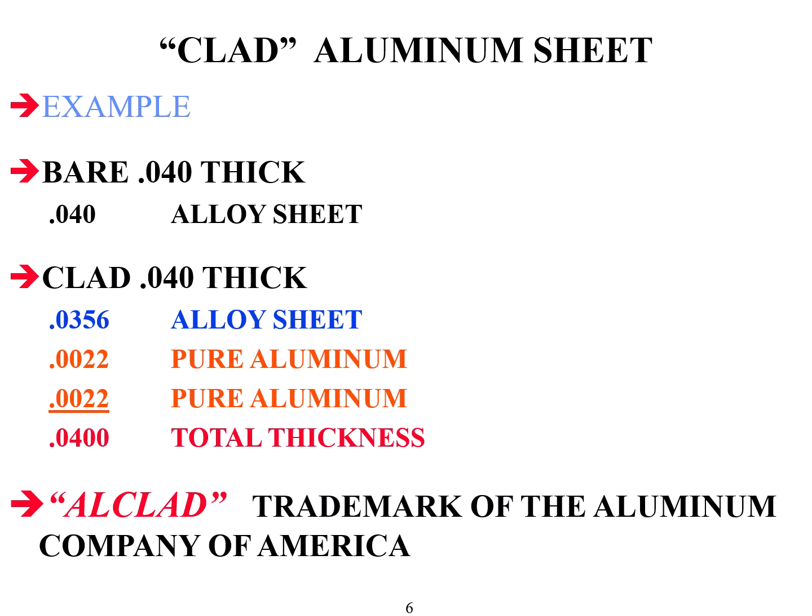The term clad added to aluminum sheet means that both sides of that aluminum have been coated with an industrially pure aluminum coating. It's very thin, and the reason it's added is pure aluminum is more resistant to corrosion than the alloyed aluminum will be.